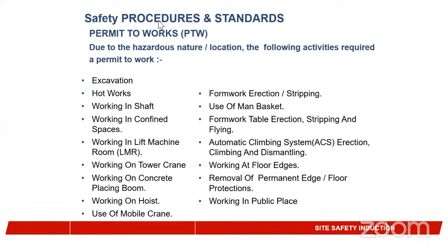Communication is key when it comes to health and safety. Like I tell workers, write your name on this permit. If anything happens to you and you didn't write your name on the permit, the company will deny you. Then immediately they write their name. I said, before you write your name, understand what you want to do. Understand the hazard, understand the risk, also understand the checks that have been given to you. Are they in line with what you want to do? Did we provide all these things for you? And you say yes, and you sign on it. Simple. So communicating permit to work based on various activities is very important.